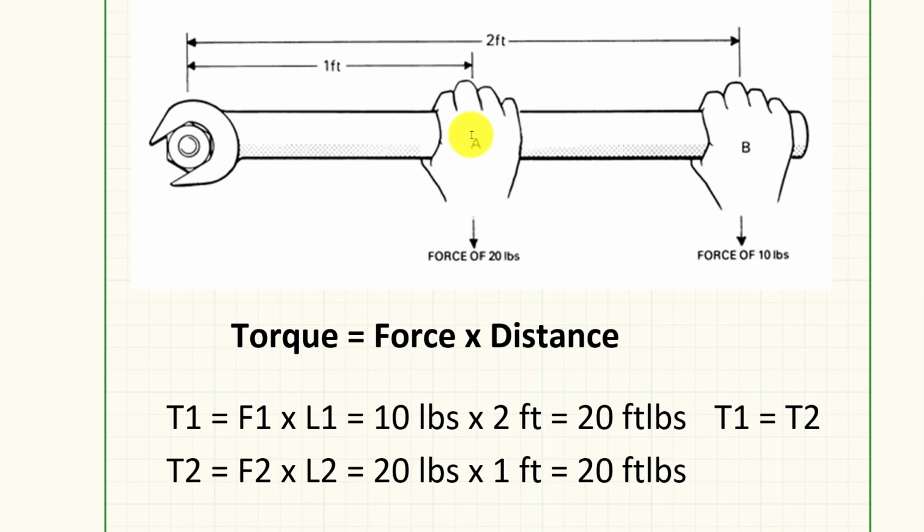Now that load is going to come at some distance. So we need to measure the exact distance from the center, the linear distance coming out here. Your wrench may be up at an angle and the weight coming straight down, so we want to get that linear distance, the correct distance there. This one's nice and straight for us.